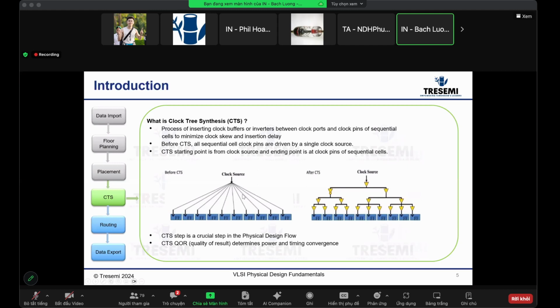So it'll stop at the endpoint of a flop. In a case where there are clock gating cells here or a divided clock structure, it will trace right through it. That's what I mean by trace through. It will not stop there. It'll stop at regular flops or a sync pin or a stop pin that you define.